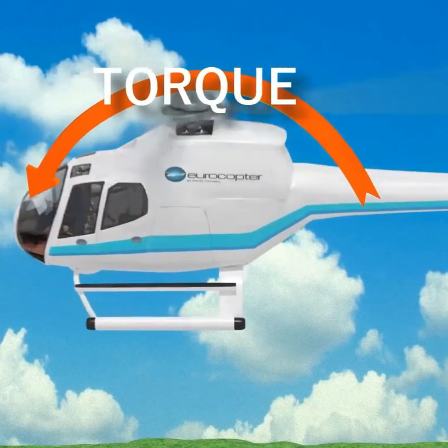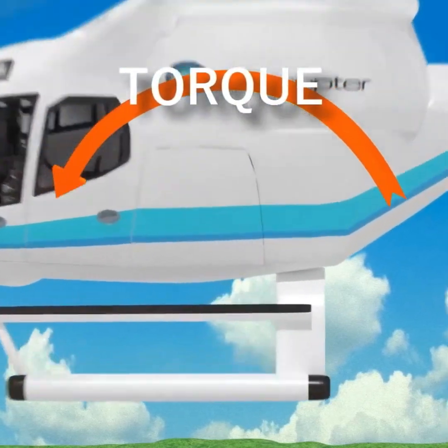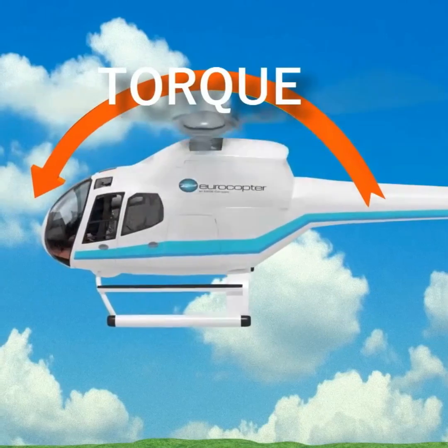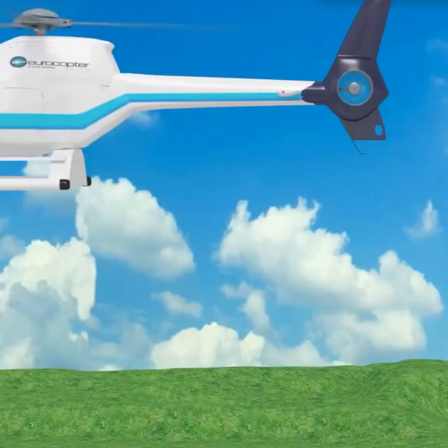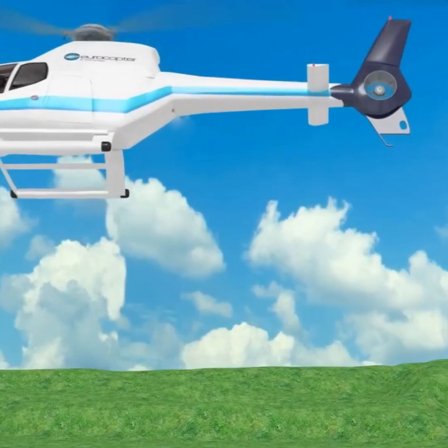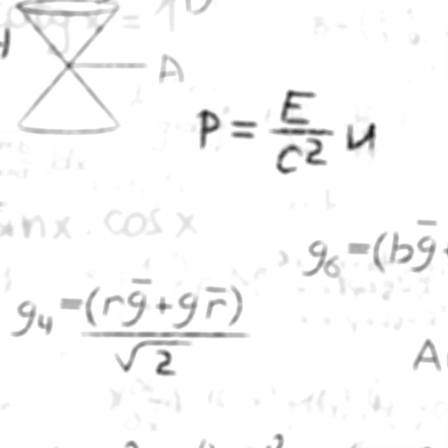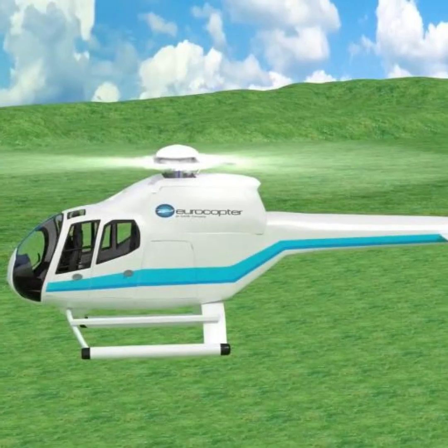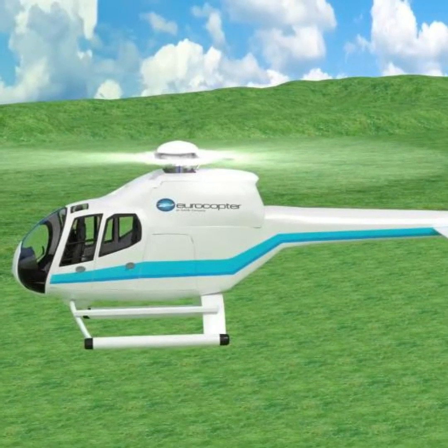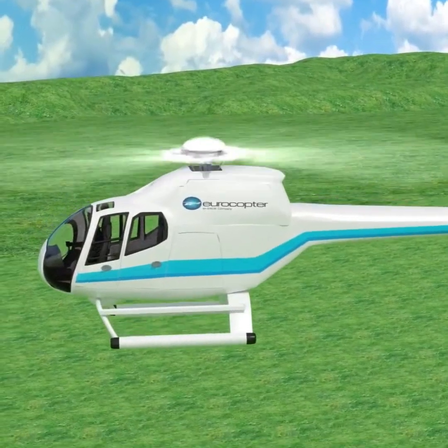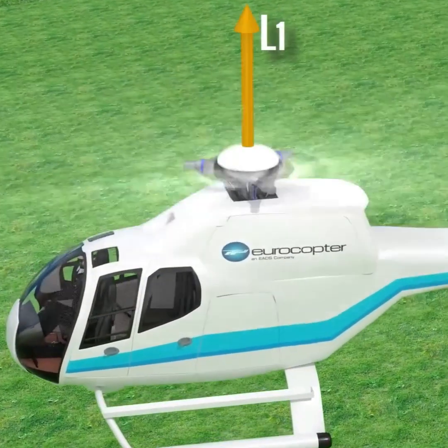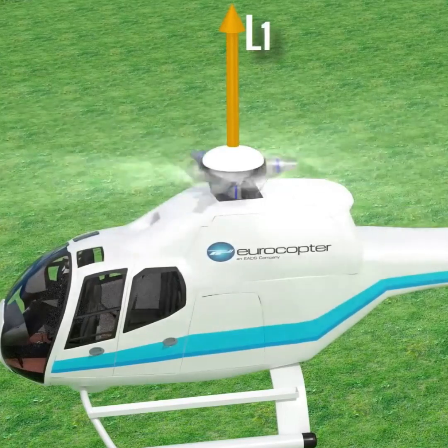Gyroscopic precession is not a new phenomenon in physics. If you look closely at Newton's second law of motion on a rotating object, you will be able to form a preconception of this phenomenon. According to Newton's second law of motion, the torque is equal to the rate of change of angular momentum. Let's think about this rotating blade. As shown, it has an angular velocity.